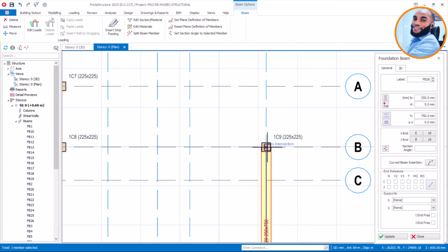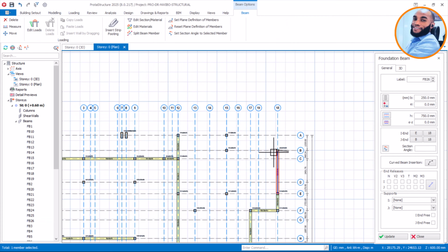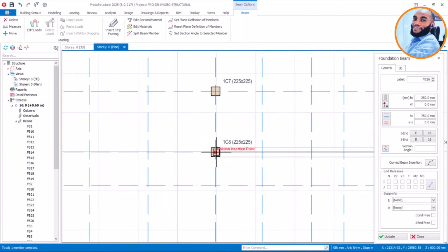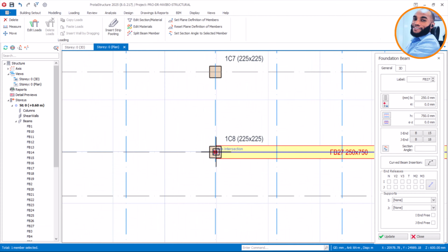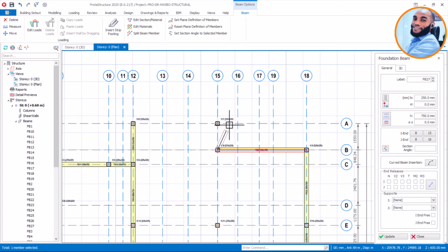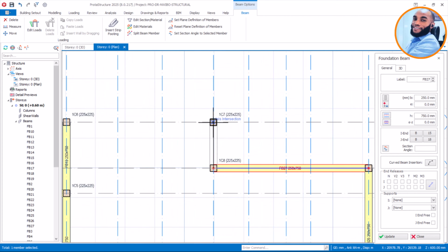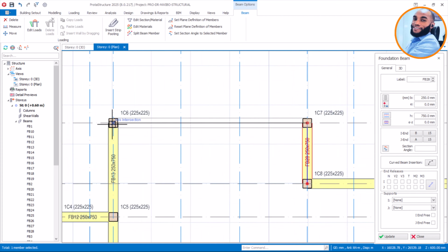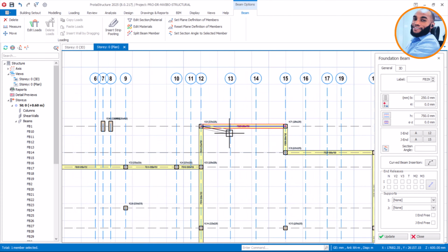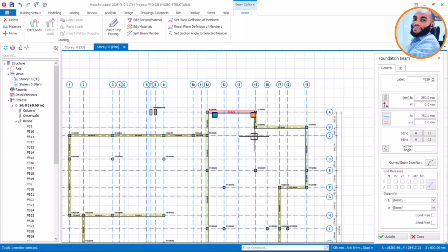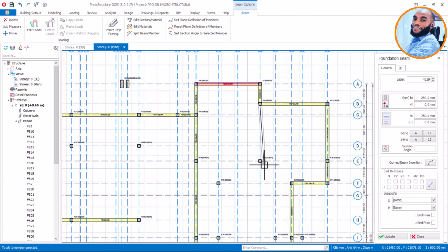After we have done this, we'll move on to designing for the footing first. Then once we're done with the footing, we'll move on to design for the beams, for the ground beams, which I'll show you how to design. Also how to arrange your reinforcement, because most times if you don't arrange your reinforcement well at site during the construction, you'll be having issues. Okay, that is fine. So I'll escape now and then continue again from here to here.